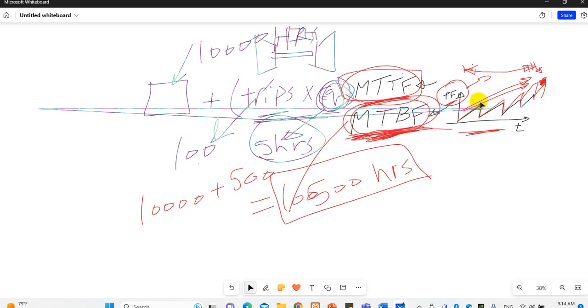Then you take the decision to make this overhaul at this point, and by making this overhaul, the result is reducing the probability of failure. And still running the equipment once again, the probability of failure increases until you reach the overhaul time. When you do the overhaul, the probability of failure goes down. That means you are increasing the reliability of the machine by doing this overhaul.